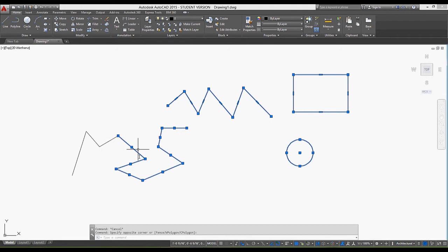The reason why this hasn't all selected is that it's not a polygon or a polyline, and this is a polyline. That's one of the differences between a line and a polyline: these are separate objects within one command, the line command, whereas the polyline makes it a continual line and object. With these, I can just select them and they'll also add to the selection. If you ever need to deselect anything, if you hold down the shift key and then select again, that also deselects it.